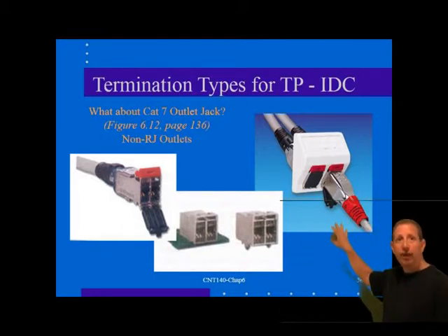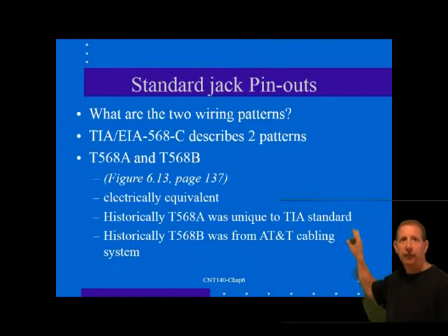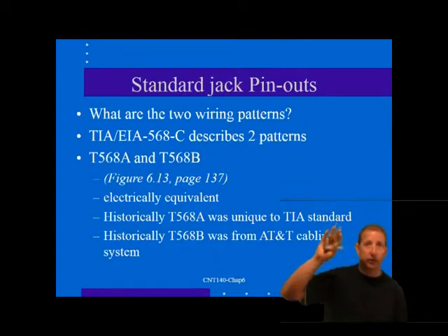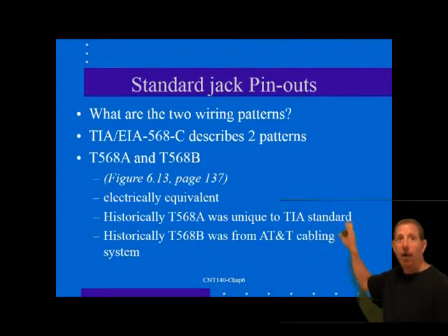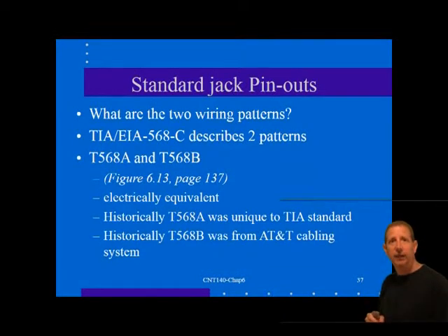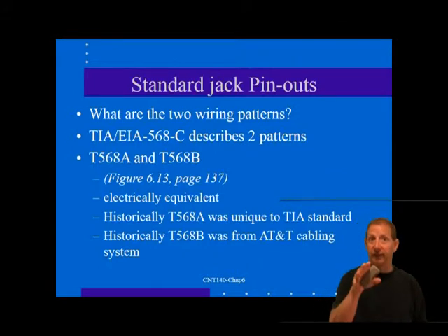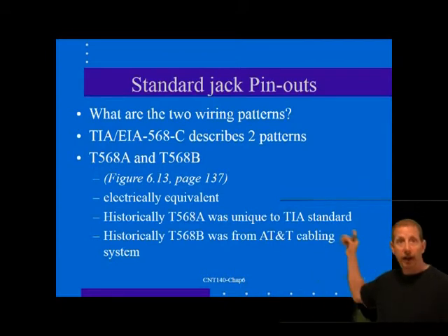Now, standard jack pinouts need to be discussed. The standard pin connections for a variety of modular jack styles are shown here. Now, modular jacks are used for many different purposes, of which LAN wiring is only one. The 568 standard describes two different wiring patterns for wiring the 8-pin modular jack. The two patterns are called 568A and 568B, and they're shown here.